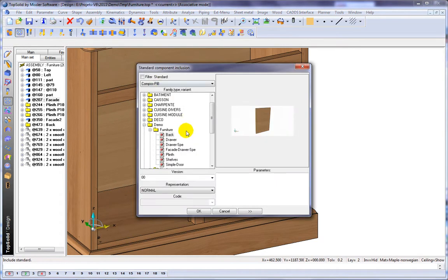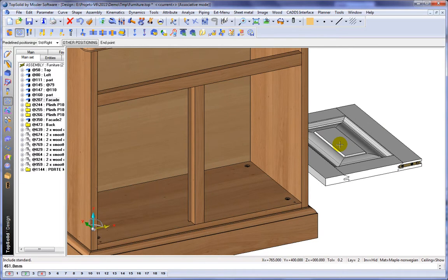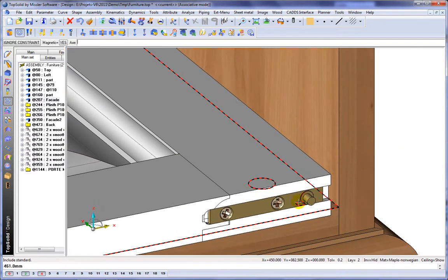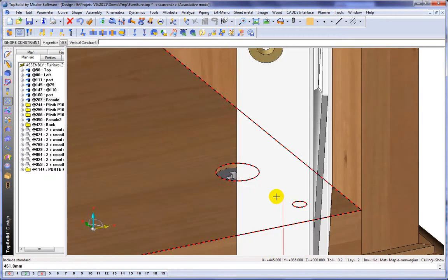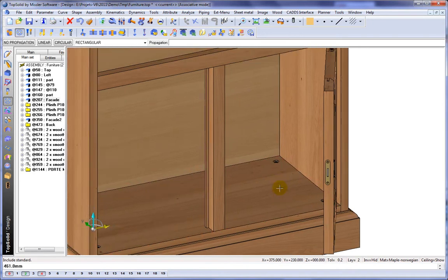And now here let's add some more components. How about we start with a door? So here what we're going to do is measure from there to there, give it a little clearance, and yes, we're relating this parametrically, and we'll measure again that length plus a little clearance, or I should say minus a little clearance. We'll locate our design. We want a right-hand door, and basically what we want to do is locate it right there. And like that, our door is inserted.